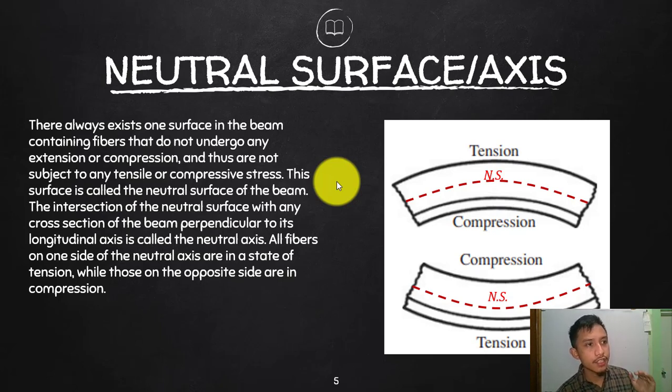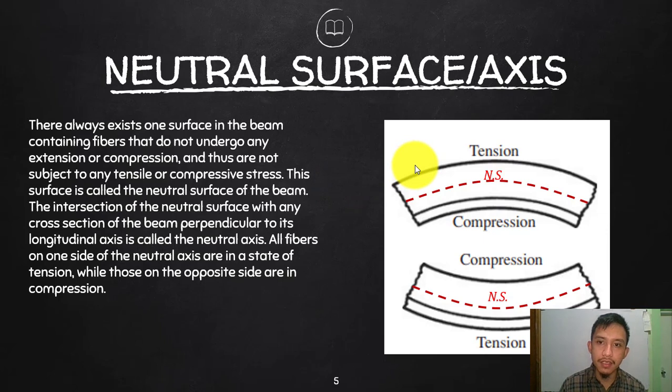The shear stress in a member under torsion increases as the distance increases. The distance that we are referring to is the radial distance, which is from the center. So that is a variable stress, same as this bending stress, or flexural stress. We call this one flexural stress or bending stress.